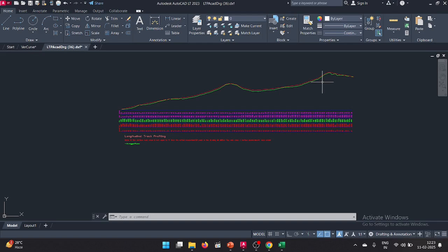So when we are doing that job, automatically the complete track level will be disturbed. During the downtime, after doing the screening, we have to take levels, and the perfect longitudinal profile should be set. Further, we also take levels. We take 5 levels in every 10-meter, 15-meter or 20-meter interval.